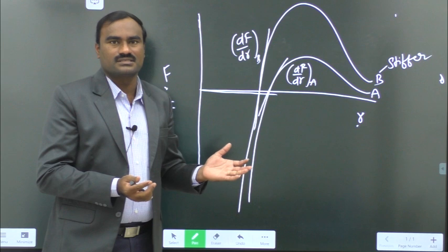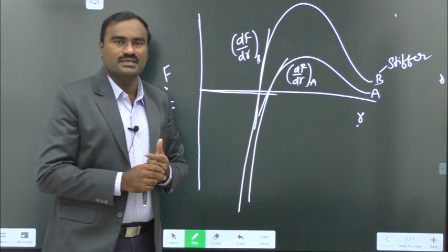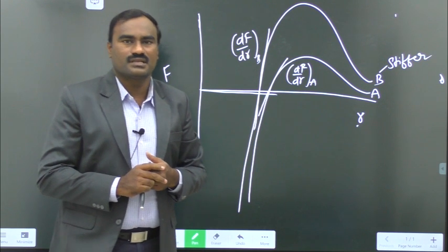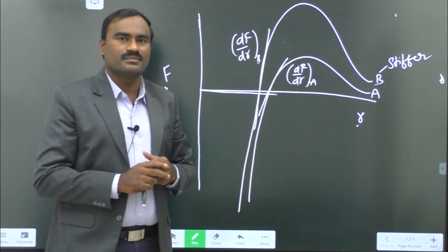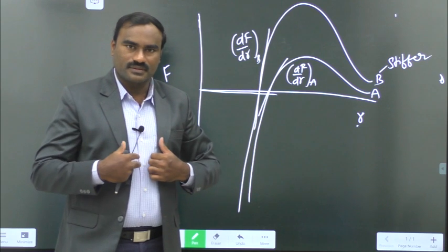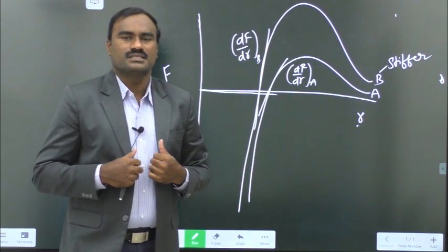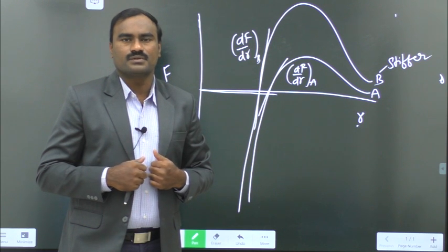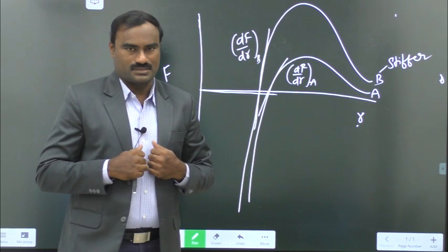So Young's modulus is equal to the stiffness of the material. We have seen Young's modulus for different materials such as magnesium and tungsten. For magnesium, the Young's modulus is 45 gigapascal, and for tungsten it is 407 gigapascal.